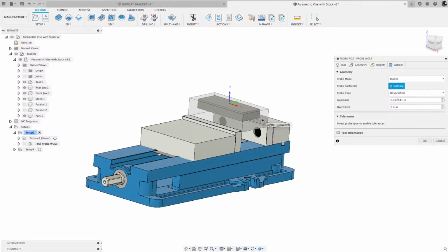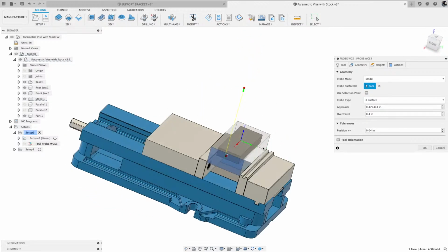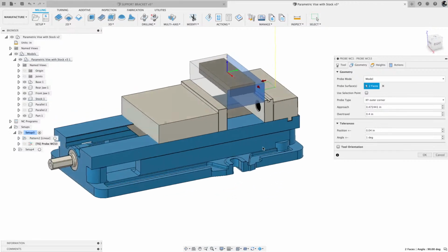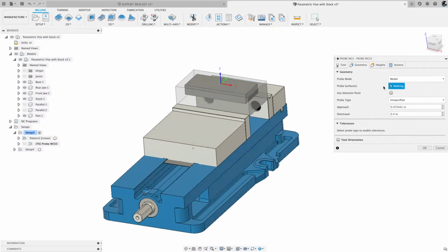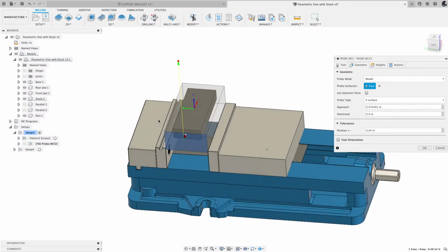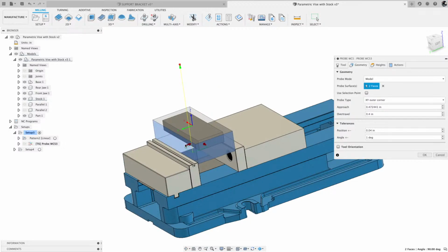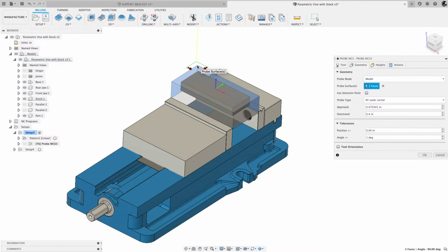But we can also do some things like you can just hit one side there. What if I hit this? What will happen? It'll probe a corner. So I'm picking two faces. So you can even come over here and probe that edge and probe that edge. And now that would give me that top corner. Of course, in my setup, I'd want to define that as my 0.